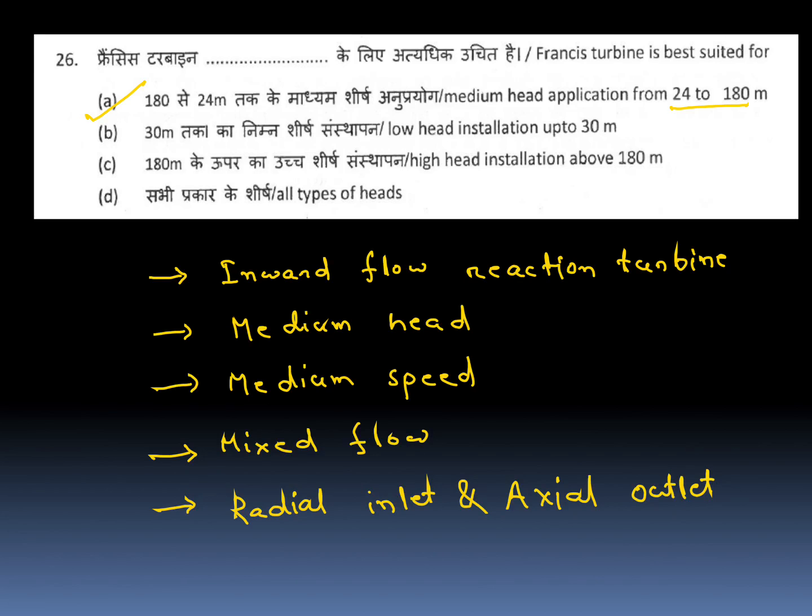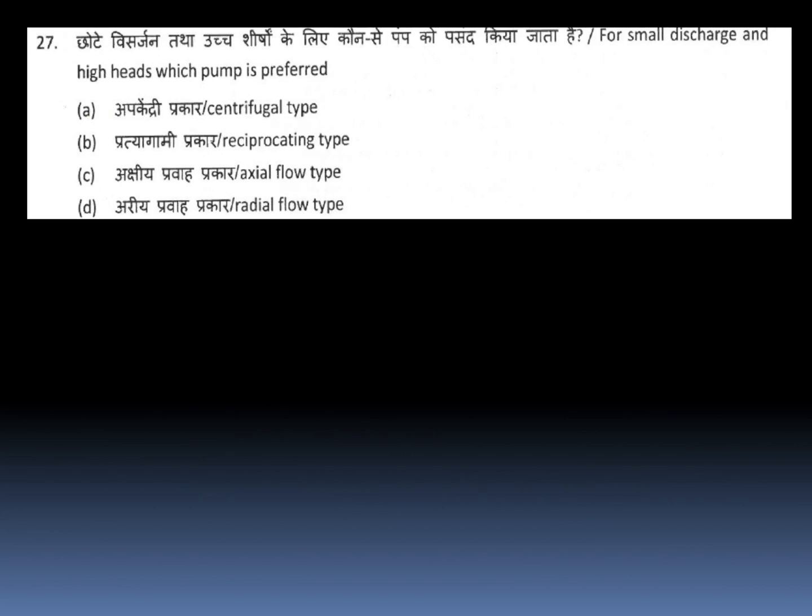For small discharge and high heads, which pump is preferred? It's the reciprocating pump. Small discharge and high head, reciprocating pump. High discharge, small head, centrifugal pump. This is also important: high discharge, small head.